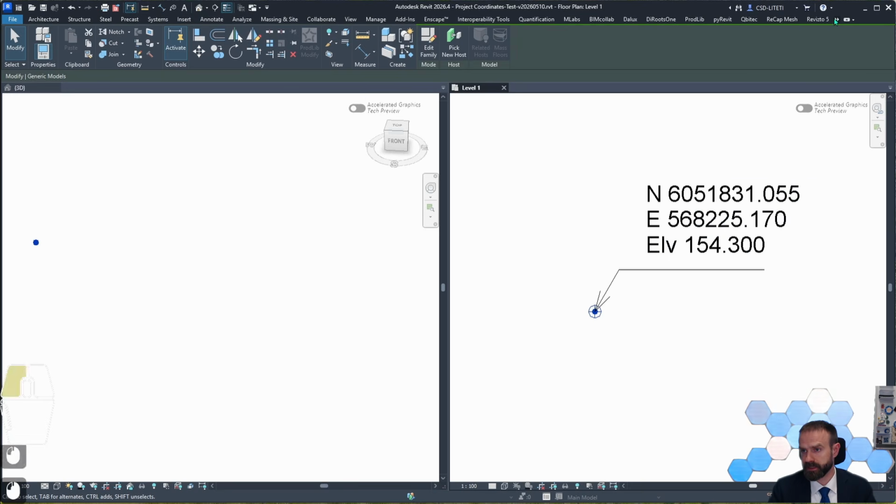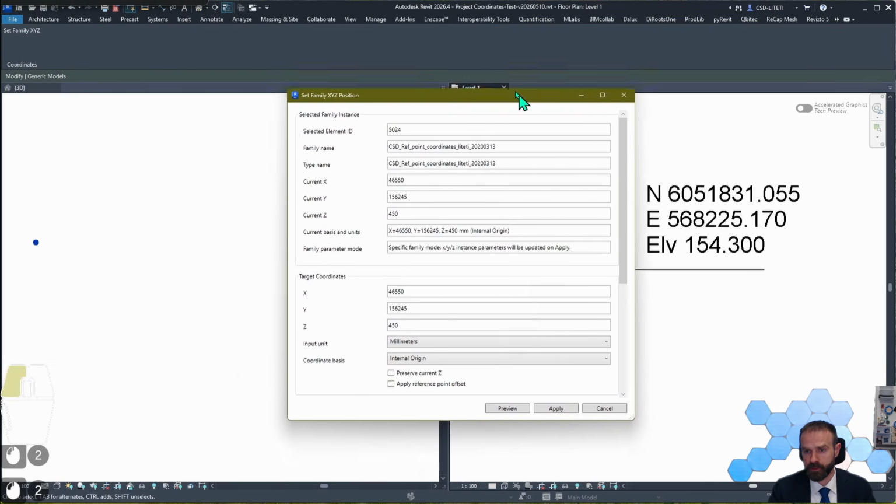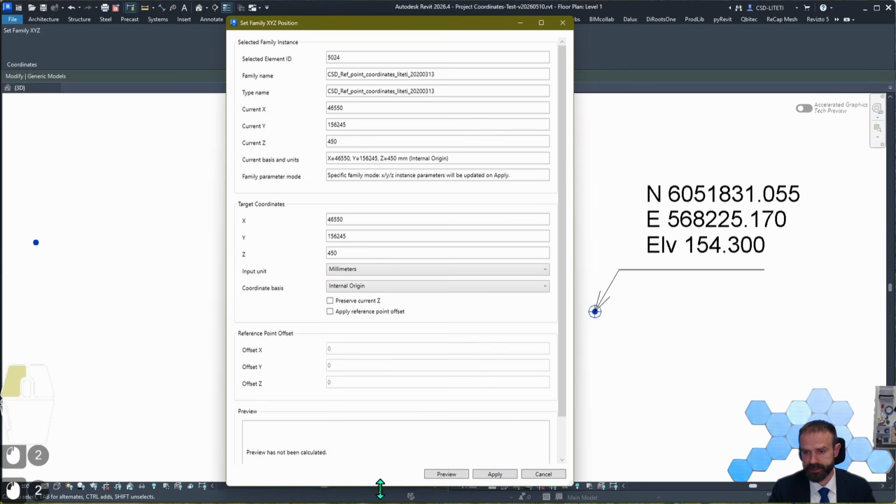So in summary, in a couple of hours, from an idea, I created a working tool which is able to set exact coordinates to any point inside Revit by entering real numbers, real coordinates inside this application, and the point jumps into the exact position in my project. So if I get any data about any point locations on my map, I can use this tool and pinpoint all these positions from a report, from an Excel file, from a spreadsheet, from a Word document, and it doesn't matter.